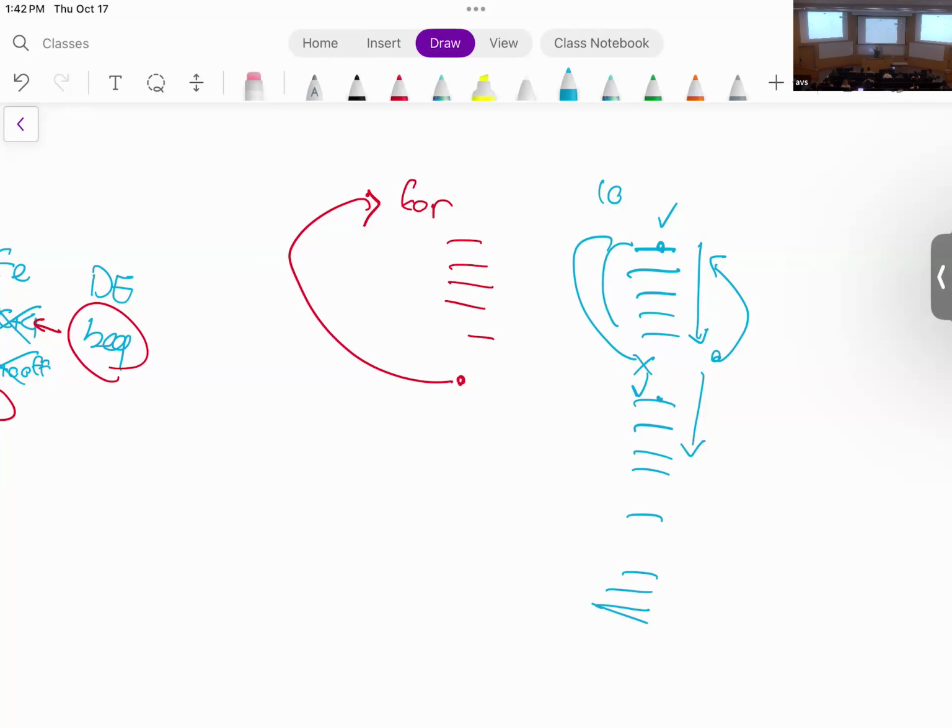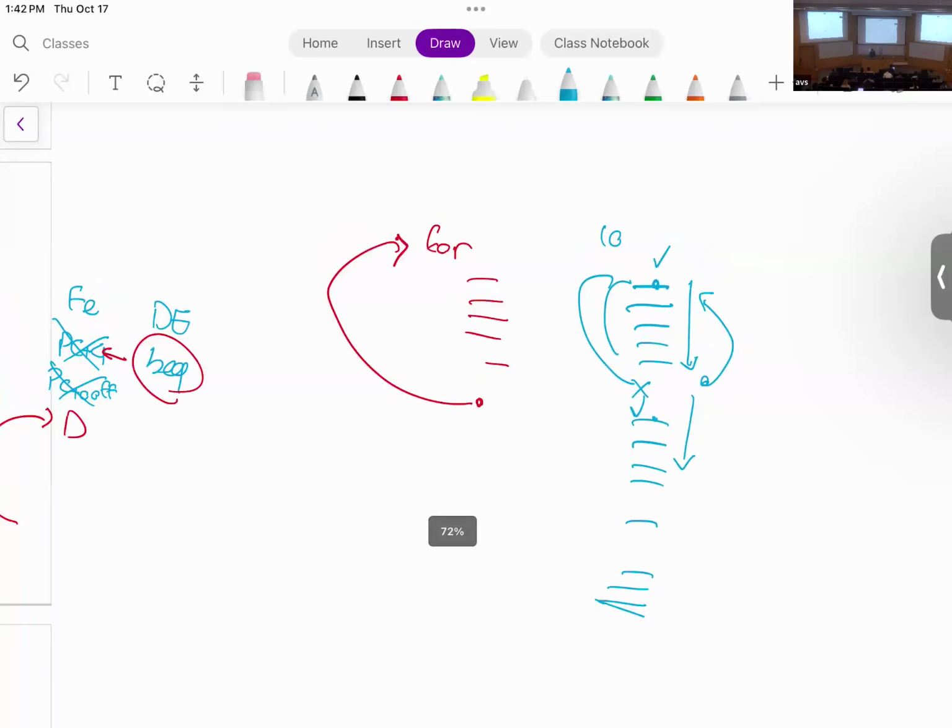Now I have 100 instructions without a loop counter. So there is a balance between the size of your instruction memory and the performance you're going to get from the branch predictor. Again, these are the trade-offs that designers have. So you can offload some of this work to the compiler so that it can help you increase the speed of the system.